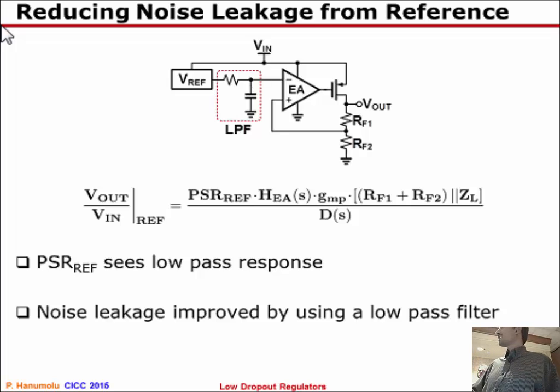But in most practical cases, the flicker noise corner happens to be less than the PLL bandwidth, which is a few megahertz for LC and maybe 10 megahertz for ring, in which case the PLL loop itself is going to suppress the flicker noise. In that case, no need to do anything special. But in cases where you are interested in absolute noise requirements, then one will have to increase the size of the output stage. So that comes with all the other trade-offs that we discussed.